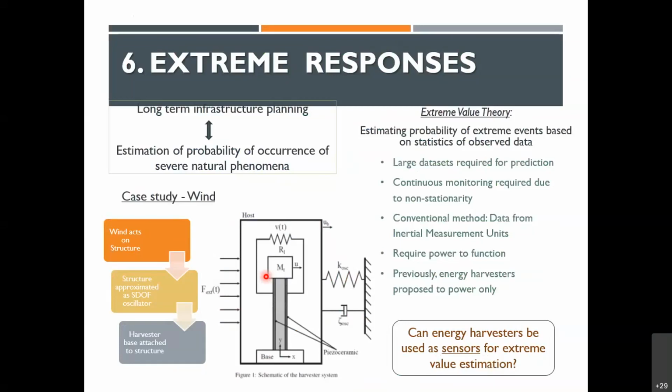But eventually, it is about estimating the tails of the distribution quite well. So if a wind acts on a structure and we keep on getting all these data constantly being logged, rather than throwing it away, we can possibly start fitting a location-specific distribution and start estimating what might be the extreme responses of whatever structure is there at that point. It might give us some extra years out of it, because it has been previously shown in various structures that if you do a structure-specific load distribution, in many cases, not in all cases, the extreme responses originally designed were overestimated by 10 or 15%.